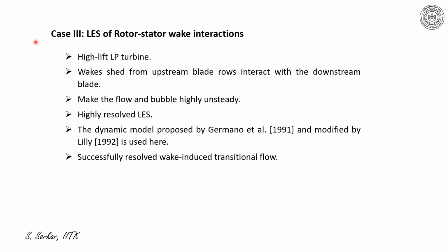In case 3, I have presented large eddy simulation of stator-rotor wake interaction, which is an important issue in multi-stage environments. I have considered here a high-lift, low-pressure turbine blade, where the blade height is considerable. Wakes shed from upstream blade rows interact with the downstream blades and make the flow and the bubble forming on the suction surface highly unsteady. The periodic passing wakes interact with the boundary layer and thus the flow is really enriched in this case.